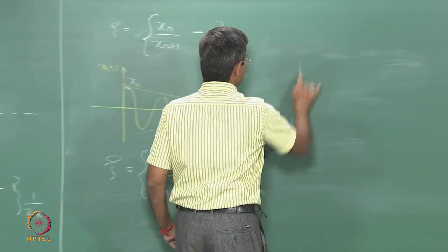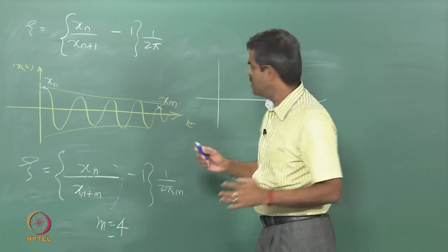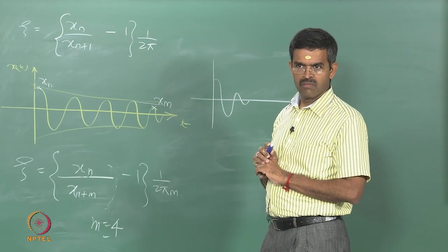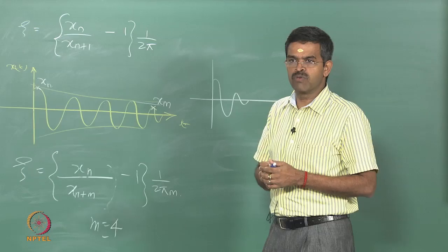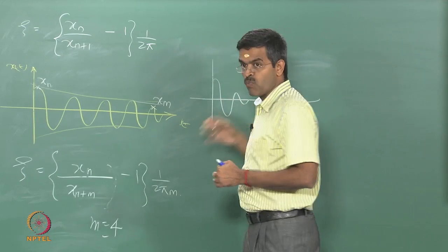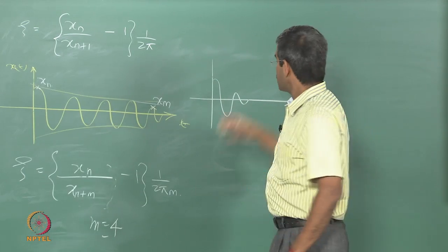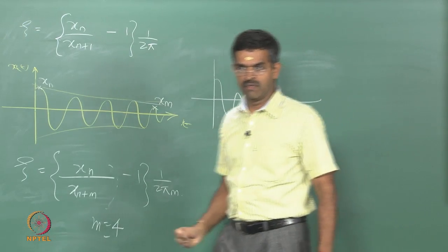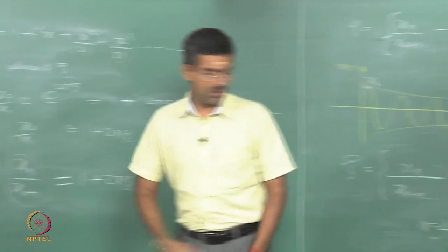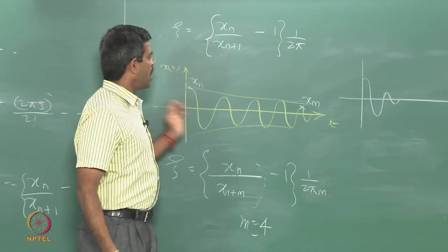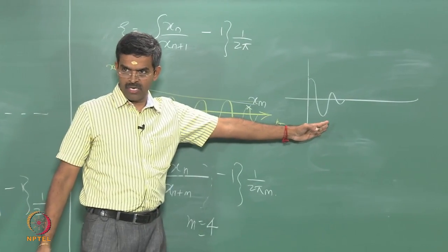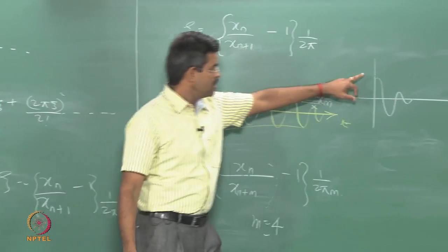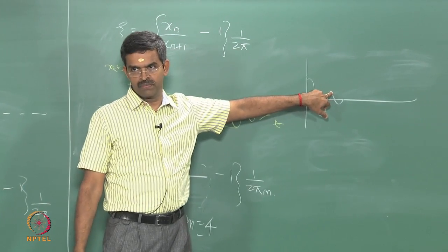Generally in offshore structures, systems being very stiff and rigid, you will not even get more than 2 cycles, because they are very stiff. They will come to dead end of the response very quickly, because offshore structures are designed to have a recentering capability, as quick as possible. So, you cannot expect a large number of cycles to come to response dead, it will come quickly. Therefore, you will have no opportunity except using the successive peaks in finding out zeta.